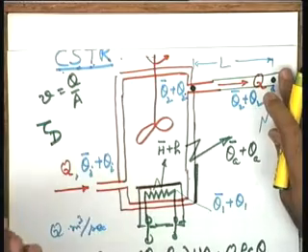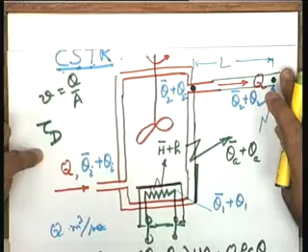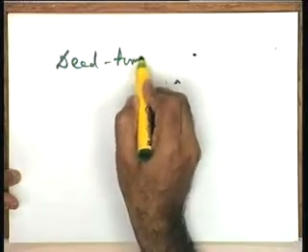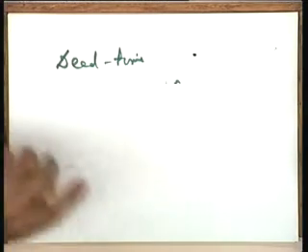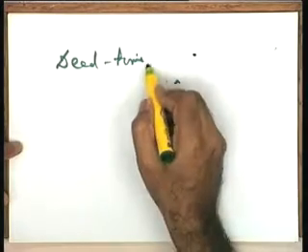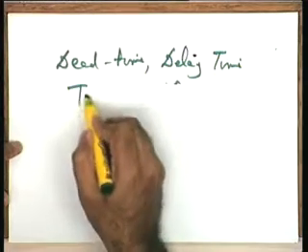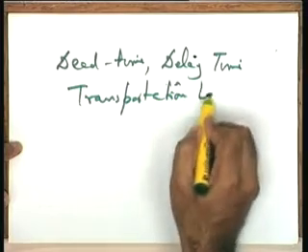I am reserving it throughout the course. The tau d, the delay time, or in the literature it is also referred to as the transportation lag. I would like you to really get these terms very clearly. Dead time, because this is the dead time, the nomenclature is obvious. This is the time which the system is not using. Delay time, transportation lag. Ideally you would like that such a thing should not happen.